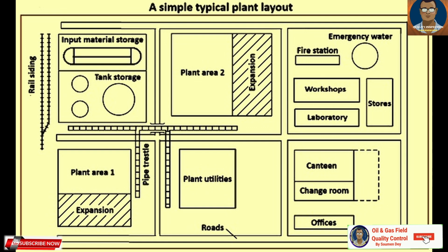Generally, the block concept is prevalent in plant layout, where the entire plot area is divided into blocks. The size of the blocks depends upon the facilities to be accommodated. We should consider a few points while locating the blocks. Process unit blocks shall be centrally located with a straight approach from the main gate. The blocks shall be arranged considering the prevalent wind direction so that flammable gases are not carried by the wind to a source of ignition.